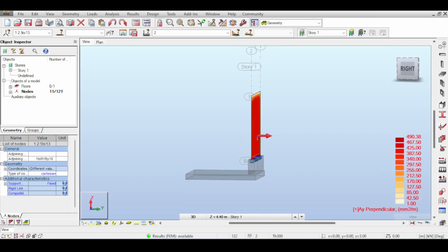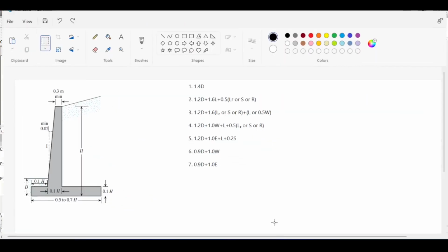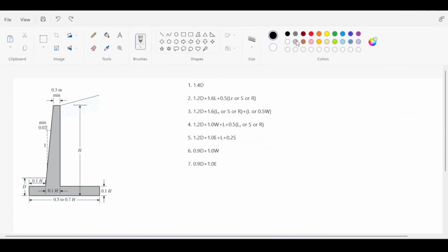a retaining wall foundation. And what ends up happening is that we, as geotechnical engineers, rely on this heel in providing us with stability against overturning and stability against sliding, because this soil weight above the heel provides a counter moment that withstands the tendency of the retaining wall to overturn.